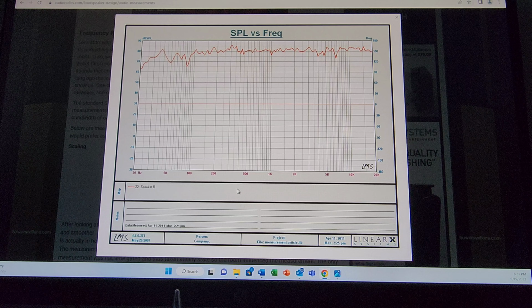Now on this side of things, and we'll go a little bit deeper into this later, this is the bass side of things. This line represents about 45 hertz, and we start to see the bass dropping off at this point. It's not that it doesn't produce bass below 45 hertz, but there is a significant decrease in output, so it's going to be less audible. And on the high frequency side of things, as we start getting around 17,000 hertz up to 20,000, we start to see a drop again in frequency output. It produces those frequencies, but just not at the same output as it would maybe in these mid-band frequencies.